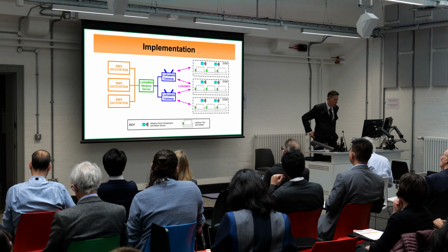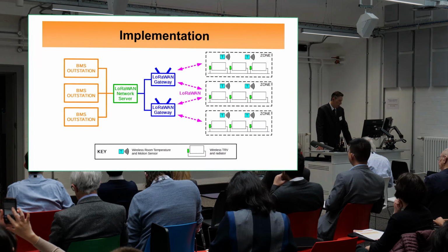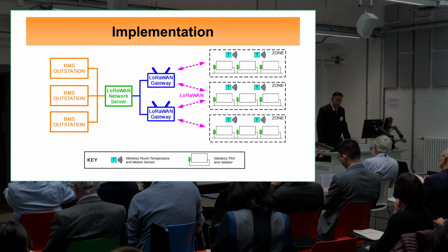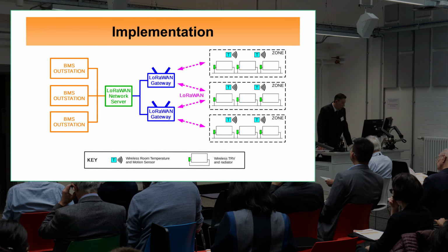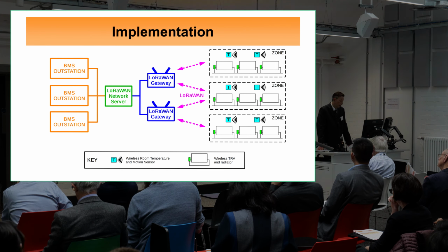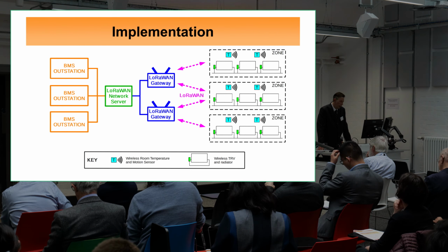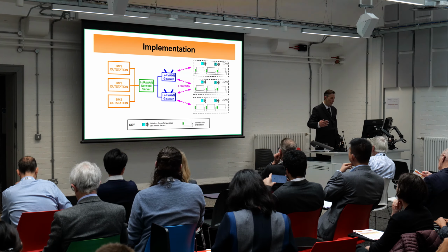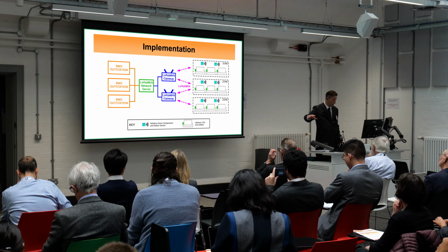So we have, using the ideas here about occupant-driven control and wireless sensors, implemented a BMS solution which combines conventional wired BMS control with the support for potentially thousands of wireless field controls, and implements occupant zonal control and demand control, allowing us to create hundreds and hundreds of control zones, so individual cellular offices, for example.